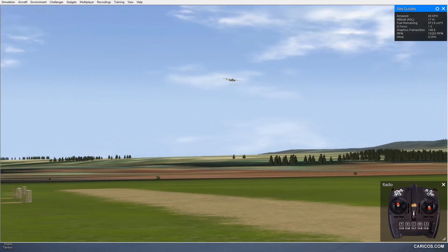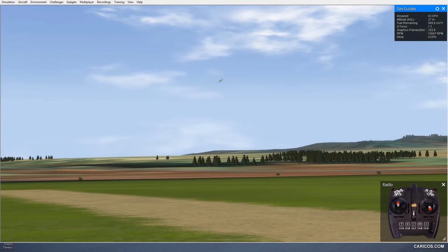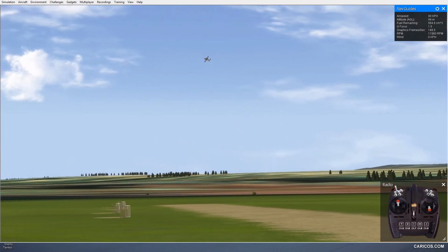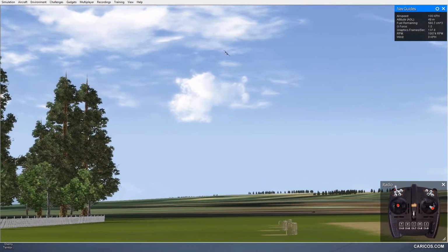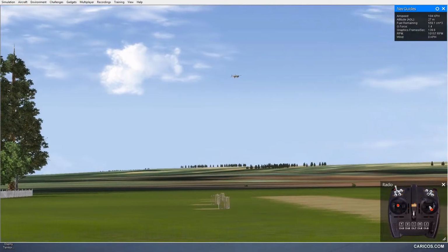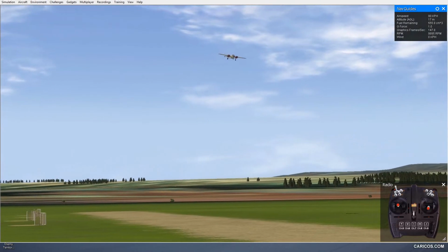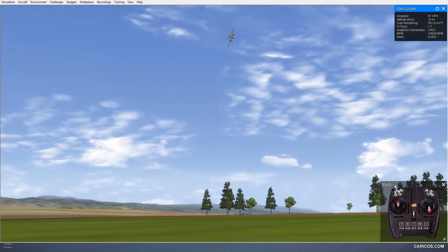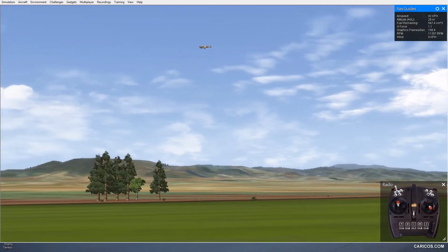And we're going to now enter in that we want to land. So we're going to start the procedure and process right now. What I normally do is I drop my gear right away here in this last leg. As I come back around to where I'm standing, I want to make sure that we have the gear out. So we see two main gear, we see a nose gear. As soon as you see that gear out, you can go fly the airplane, keep your speed up, and turn back for base leg from your downwind approach.